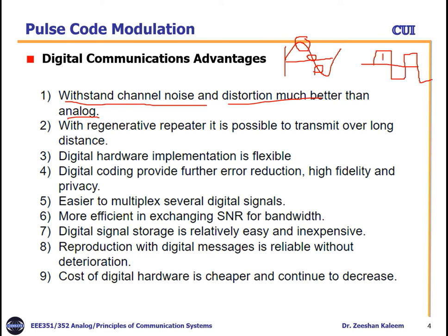So these are the levels, right? Minus 1, right? So we transmit 1 here or the 0 bit here. Even if the noise affects this one, if it is still above this value, for example, if after noise this level decreases but it's still above this line, it is positive, so we will consider that the 1 is transmitted. So they are very much prone to the noise.